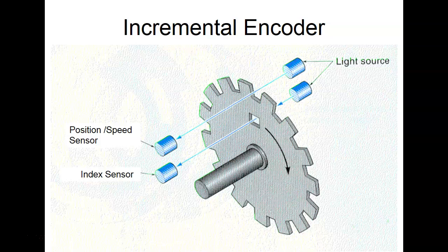They work real well unless we do something. Well, I'll show you what we do. They work real well to give us position that's moving in one direction. So these guys give us a series of pulses, and then we count them. And every count would mean something. So we use these in combination with a counter. PLCs have counters in them. And by the way, if you use one of these, you'll have to figure out what they call a high-speed counter, which would be designed to handle encoders like this.